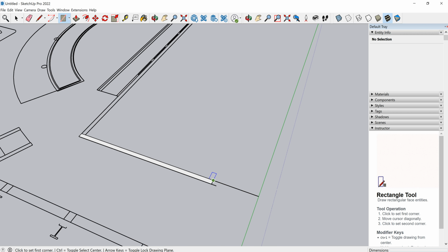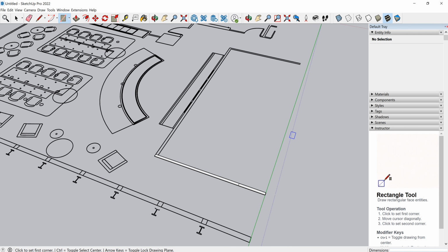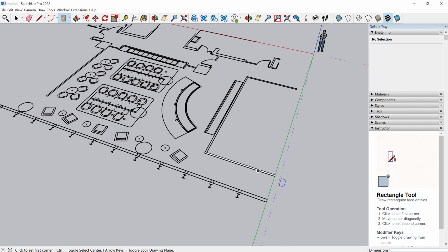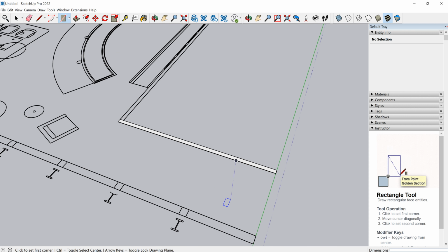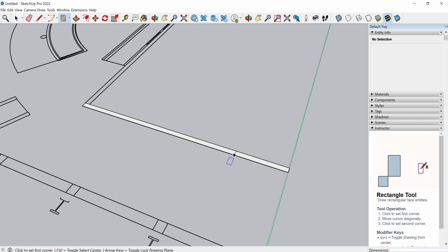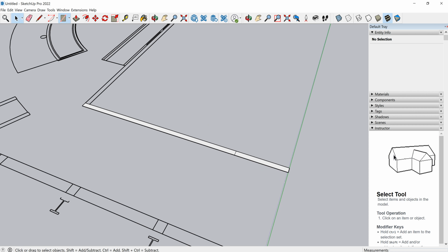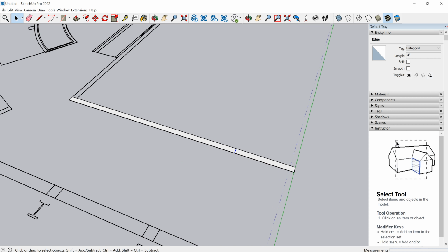Okay, so all I'm doing here is kind of extending the wall. I don't have to do this, but at the same time, I want to just extend to that y-axis of ours, which is that green line. And I just built 2 rectangles, and it just made my life easy to do that. And then literally that little line that separates those 2, I'm just going to delete. And that happens quite a lot for me in SketchUp.